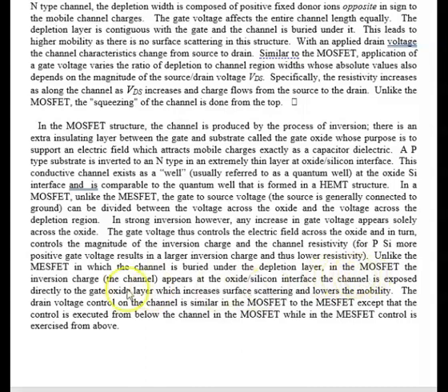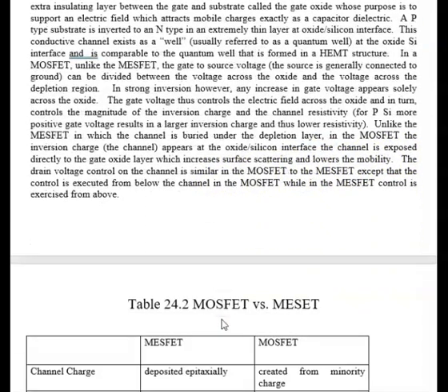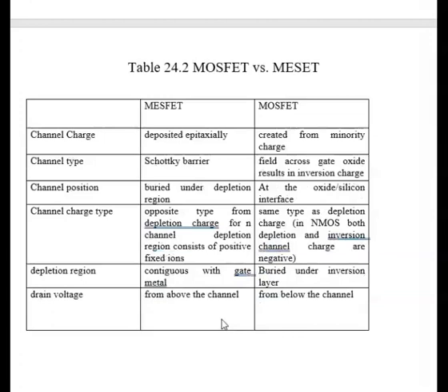In the MOSFET, the inversion layer is below the gate. So those are very, very different. And that is chalk one up to the MESFET, because on the MOSFET we have lots of surface scattering off of that depletion region. So the MESFET has some advantages there, but a lot of similarities and a few dissimilarities. So let's put that in table form.